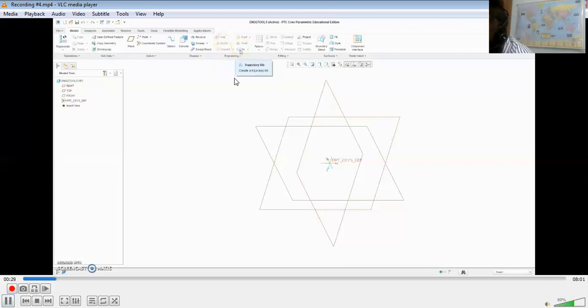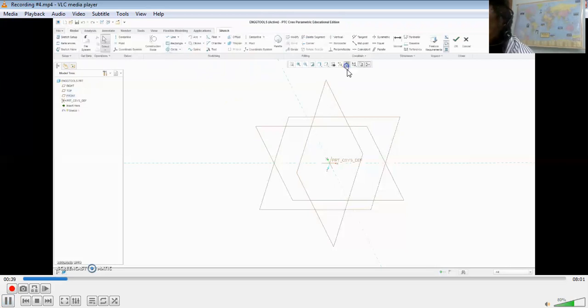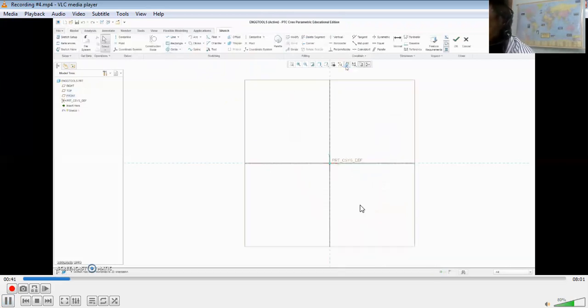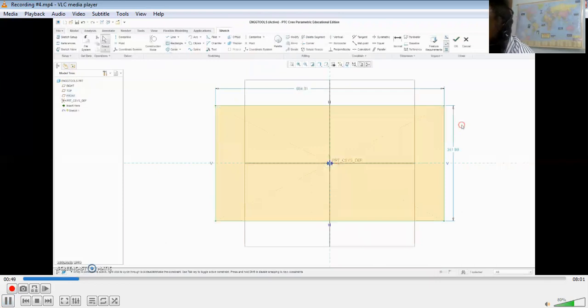all these options. To start with, the procedure is we have to create a sketch. So take a plane, choose the sketch option, and then the sketch plane for us to draw. Once that is done, I'm going to pick a rectangle and make a closed loop area.